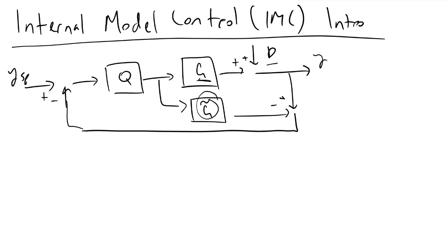And so what we'll do is first we're going to transform this control block diagram of IMC into something that more closely resembles the standardized control block diagram we're used to in closed loop transfer functions. And to do that, we rewrite our block diagram as this. So we'll still have some kind of demanded set point YSP, and we'll have an error present. And this error will enter into some kind of control block that we will make a little bit different.